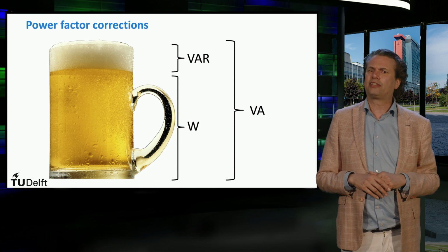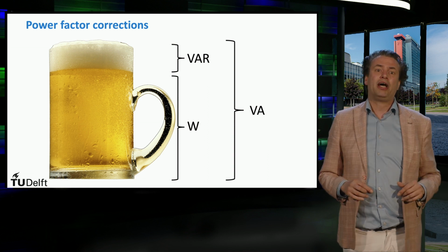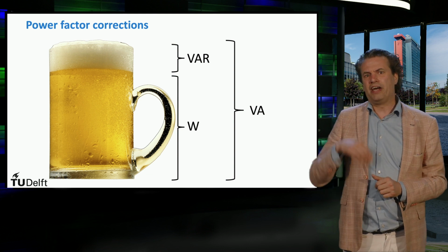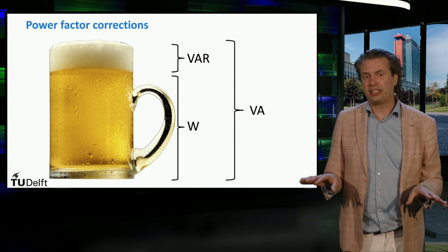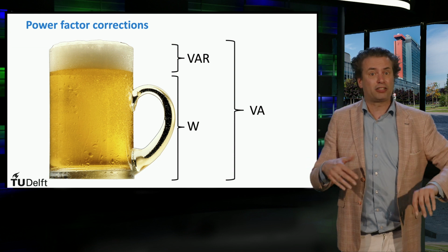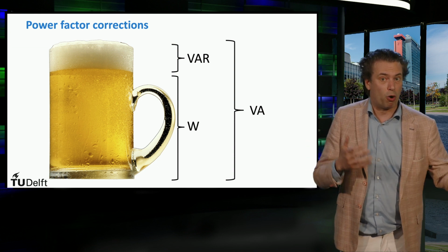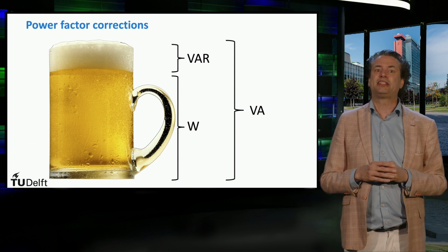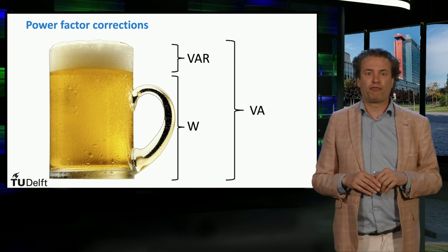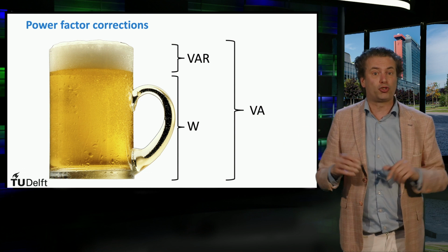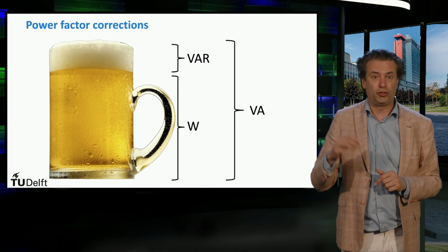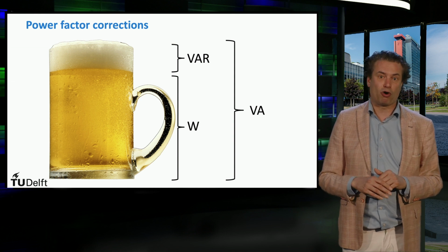We must then take into account that only real power can be transmitted and then used by the load. Therefore, a poor power factor on the grid increases line losses and makes voltage regulation more difficult. In order to regulate the reactive power present in the system, changes to the software control can enable many inverters to supply positive or negative reactive power to the grid during voltage dips or rises.